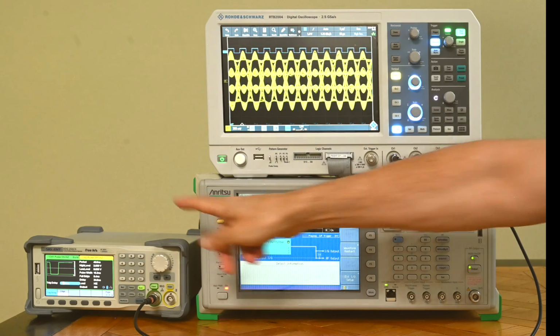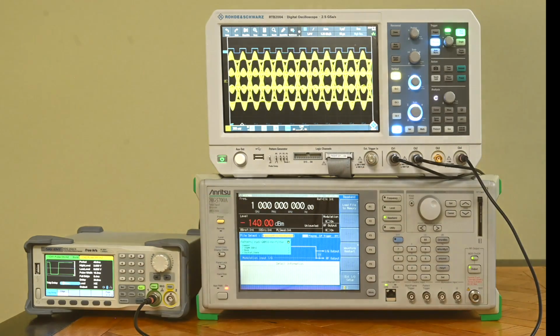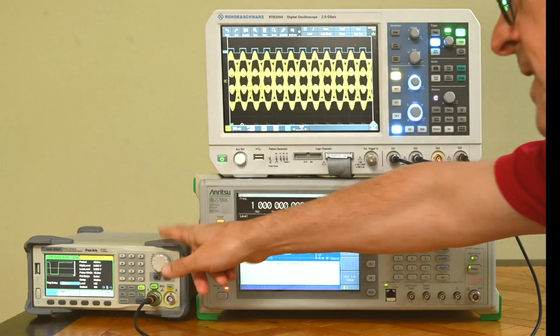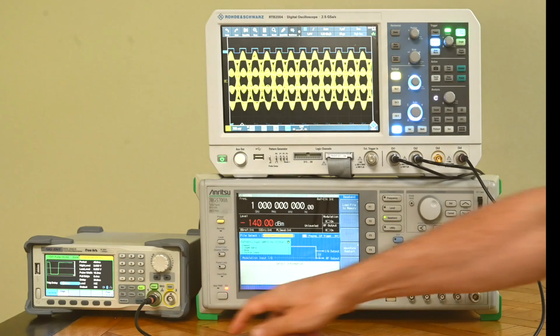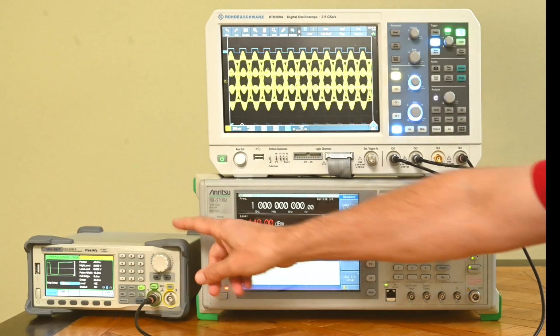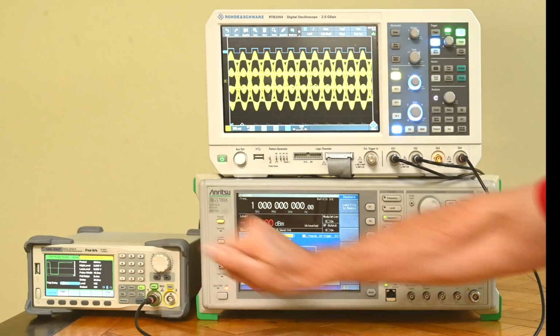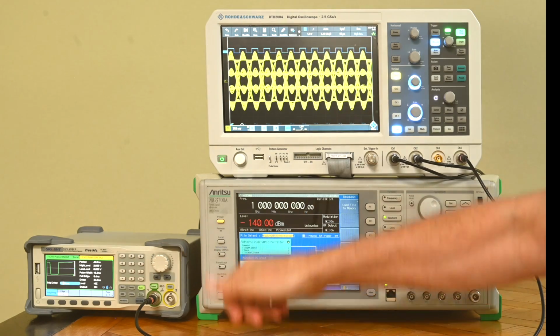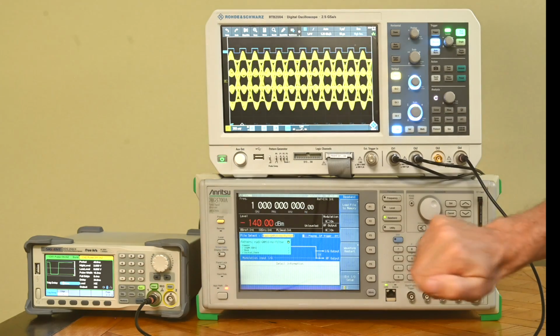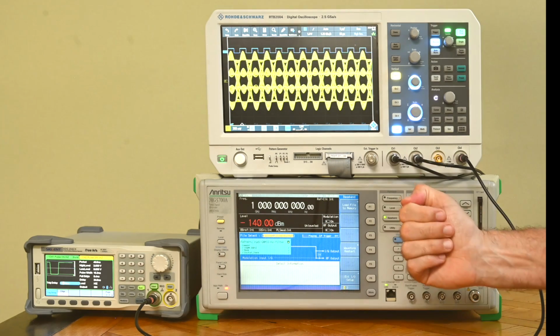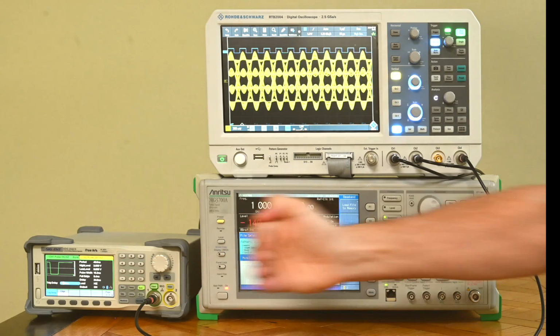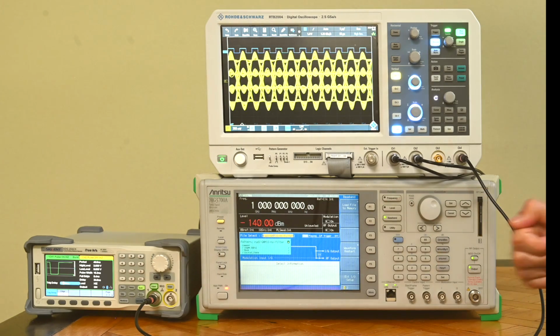Now, in order to do that, I'll be using my signal generator here. I'm using basically, I think it's called, the gate function. So actually it created the pulse. The pulse is triggered by an external input, which is the word clock here, and I can set the width of the pulse, I can set the amplitude of the pulse, but I can also set the delay of the pulse.